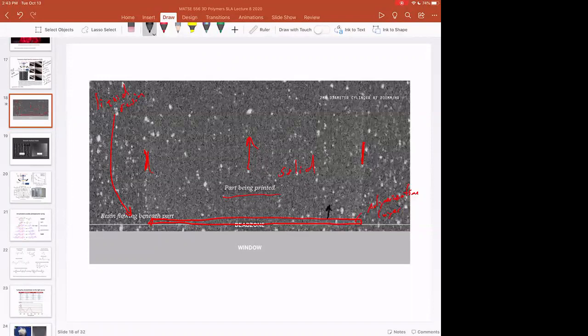for the next layer. And so that's really interesting, because even though the photopolymerization mostly turns off when the light turns off because it's inhibited, and you'll see some of these resin recipes having inhibitors in them to make sure that happens and you don't get resolution bleed and other things like that, you still have this knitting together of the layers where the different layers are polymerized basically together because they're all made out of the same polymer.